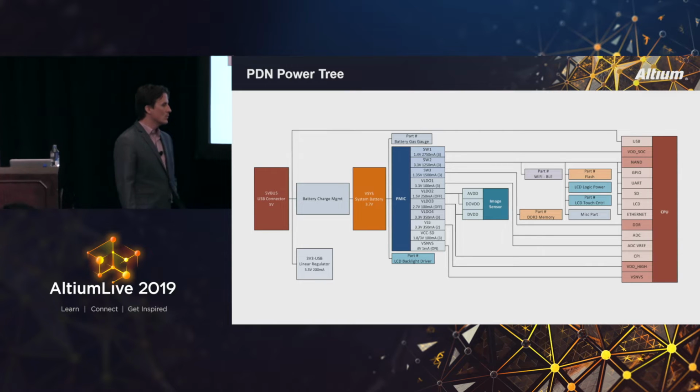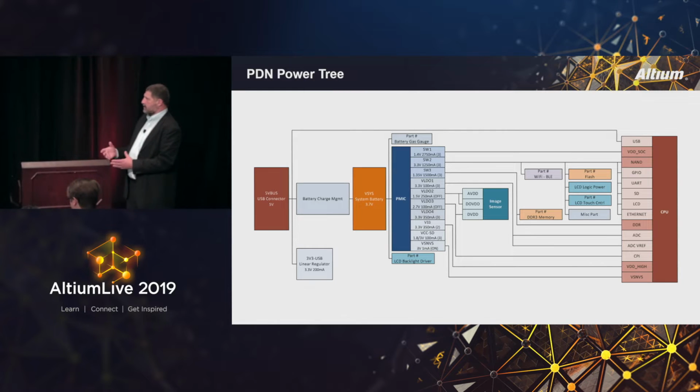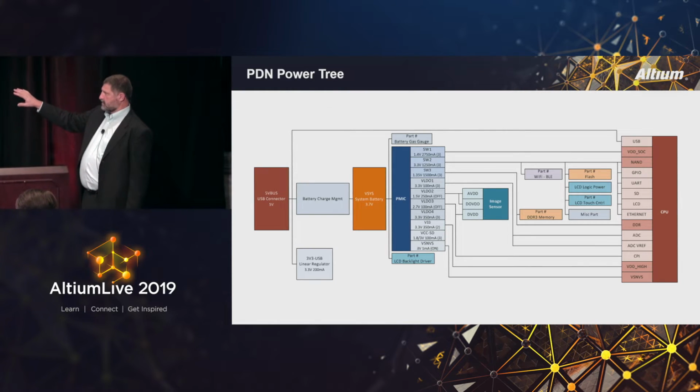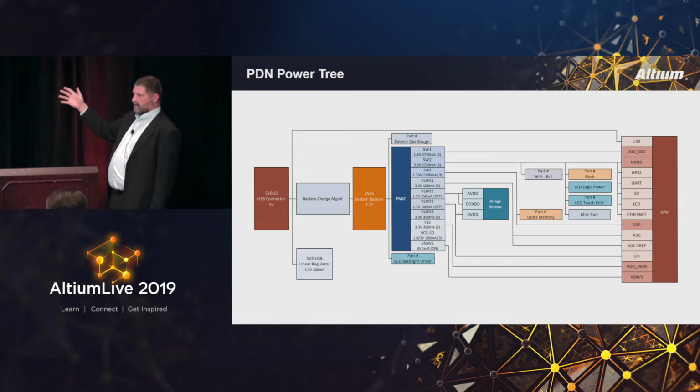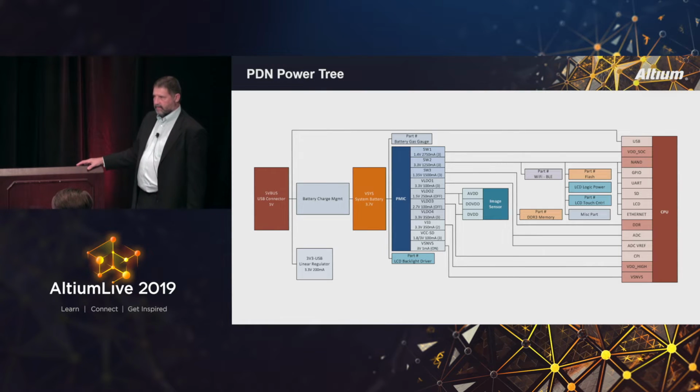Yeah, in the placement, I'm typically going to try and co-locate parts with similar power. If I can co-locate those, then I'm hopeful that I can do a split plane where I'm going to be able to break these things out in a way that's going to fan out that power to different areas of the board. So I can do a lot of twists and turns on that split power plane, but I'm really looking to use as few layers for that as possible. In modern embedded systems, it's all about power management, and sometimes these boards will get dozens or up to 100 different nets, and it's super critical to place the components in a way that you'll be able to supply power to them.